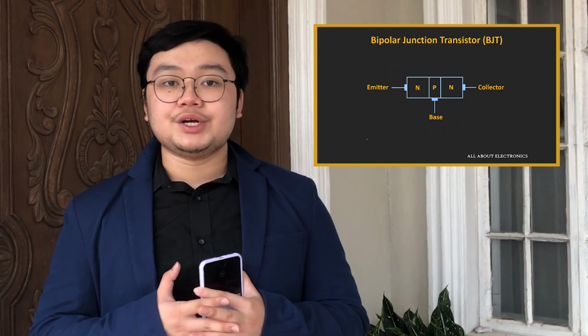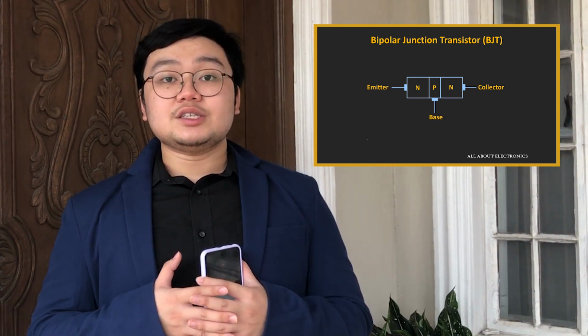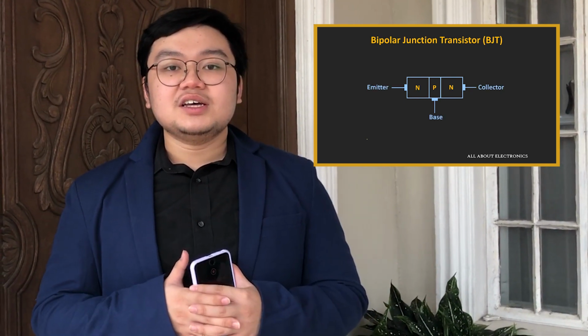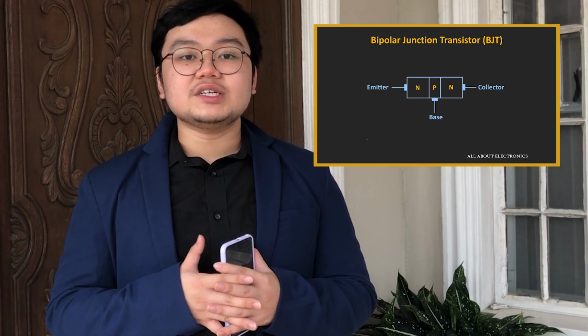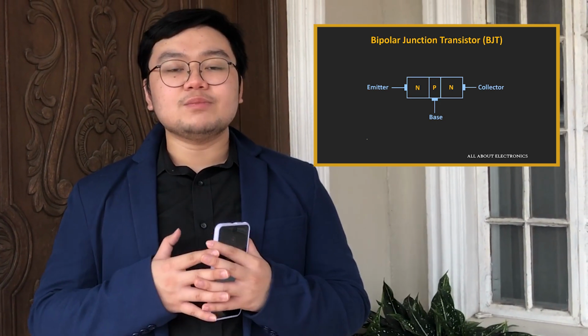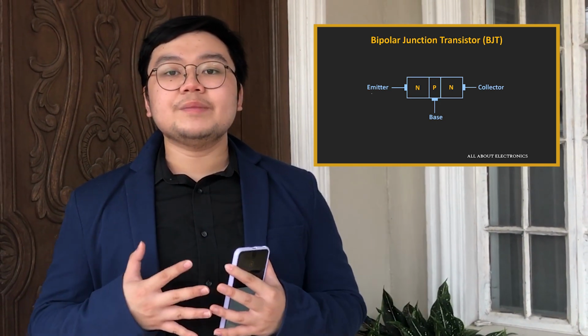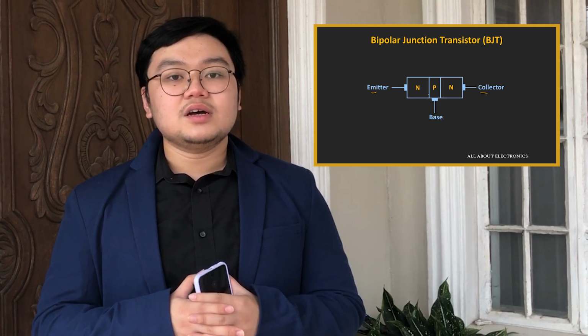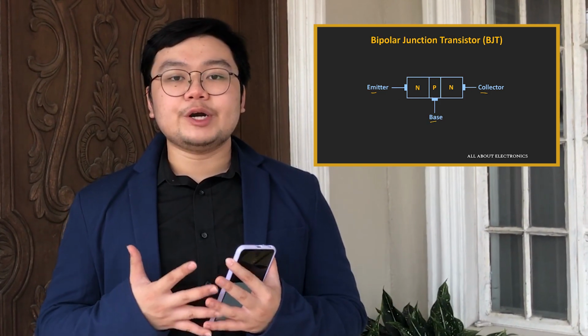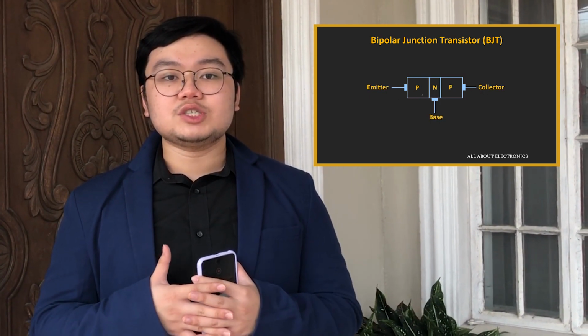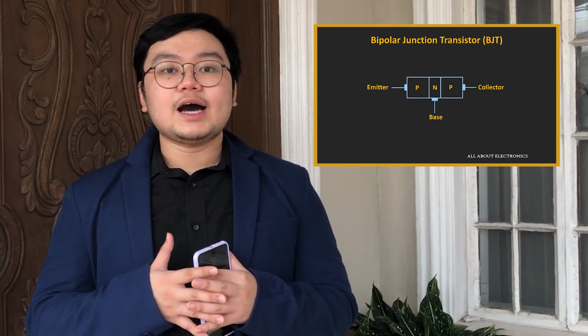The emitter of the transistor supplies the large section of the majority charge carriers to the base and is always in a forward bias connection. The collector is always on the reverse bias connection since it removes the majority charges from its junction with the base. The base is the middle section, wherein it forms 2 circuits, which are the input circuit and the output circuit with the collector.